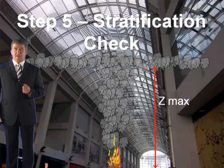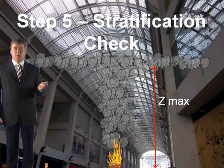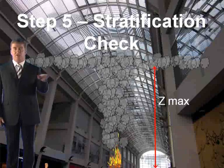We now need to start determining how we're going to extract this smoke. Before determining this, we have to consider stratification, and this is considered in step 5. Now in this building, due to having such a low clear layer height, stratification will never occur. It's too low. So in other words, although you've got to look at it, you don't have to apply it. In this particular case, you can ignore it. You go straight on to step 6.